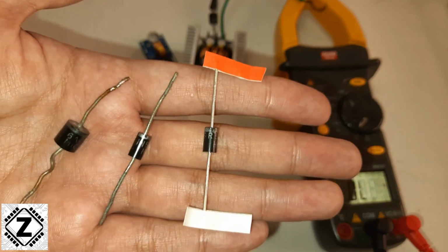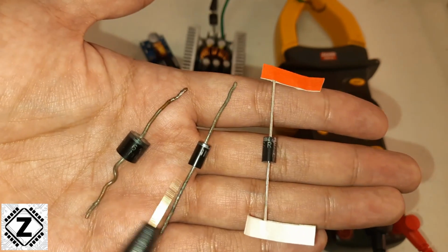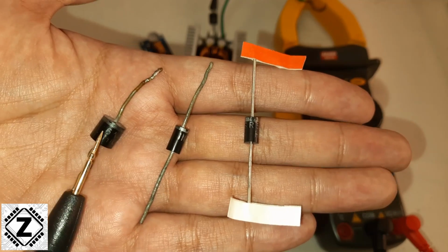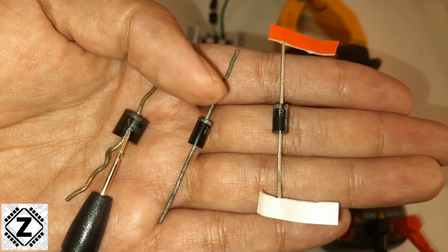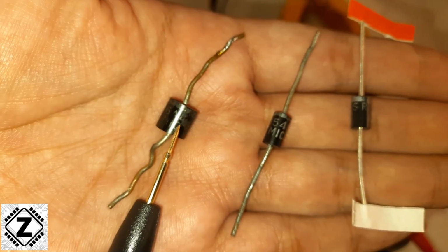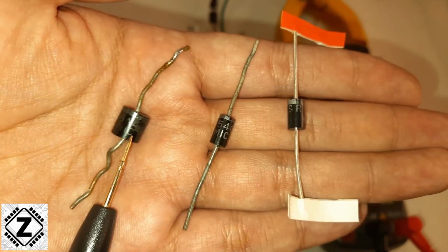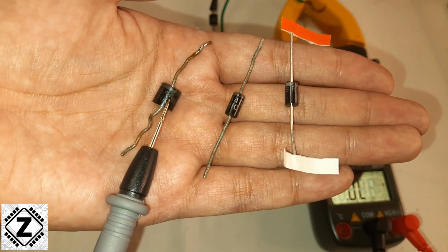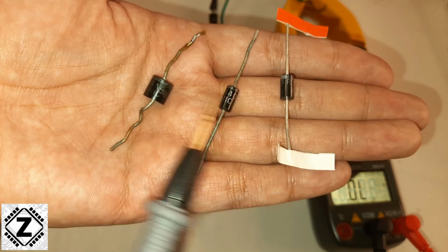The other thing is that the amount of voltage that a regular silicon rectifier diode supports is much higher. These things are generally rated for easily, for example, this one is a 6A4, 6 amp diode. It will easily support 400 volts. It's available in different varieties. You can buy them in 400, 600, 1000 volt as well.